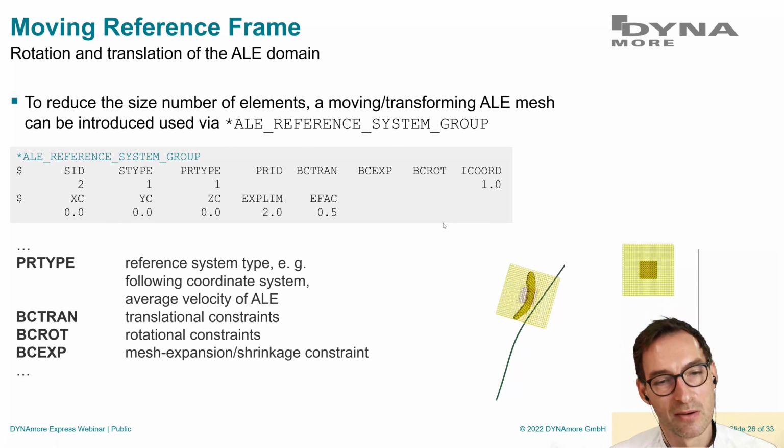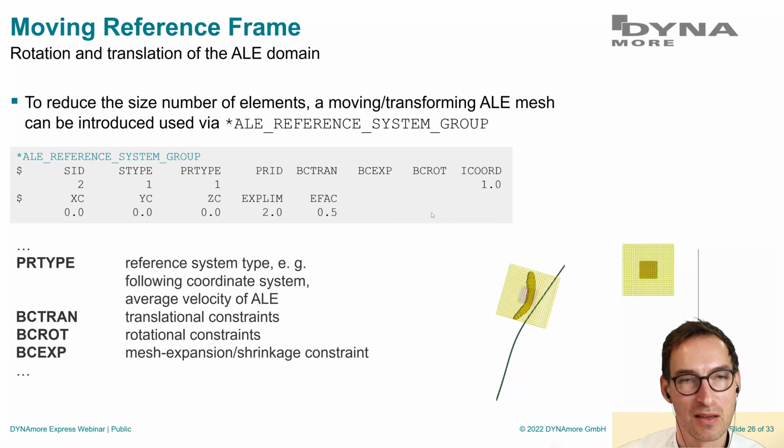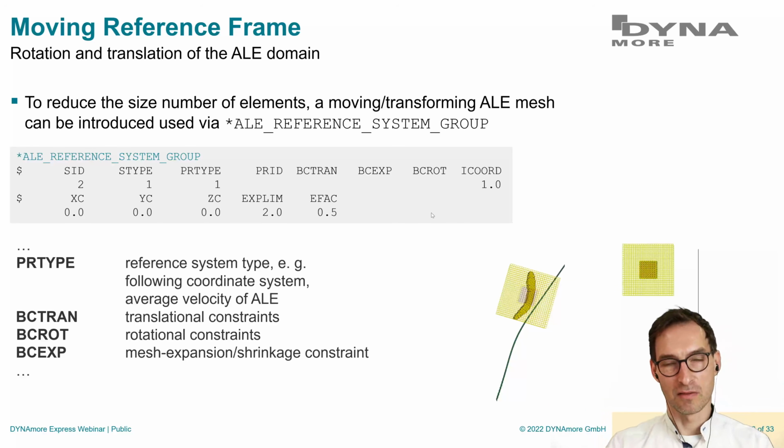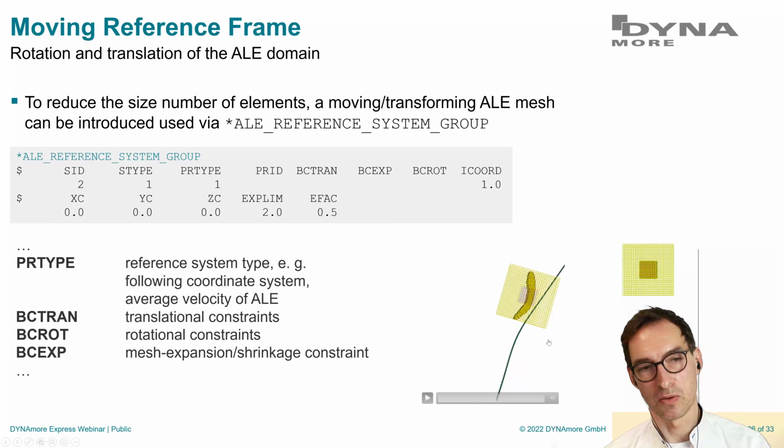Okay, this is really the last one, sorry. How do you define an infinite air domain? There's a keyword called ambient air, I think it's in the boundary conditions. So you can define a layer of ALE elements on the outside of your domain, and you can prescribe this as an ambient air, and then you can prescribe boundary conditions. This is one way of doing it.